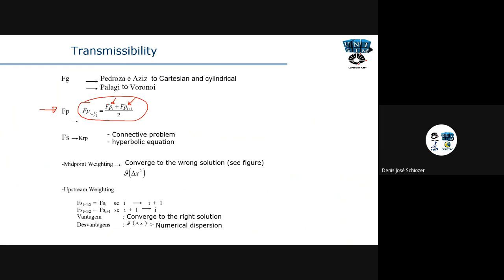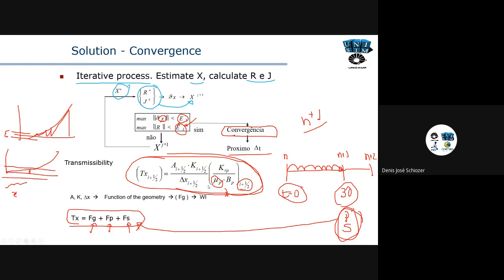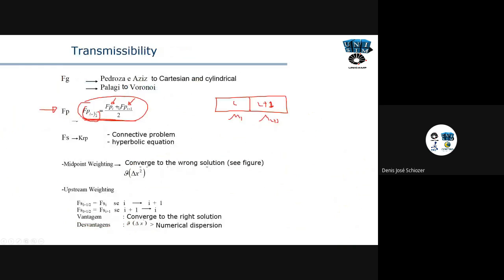So the viscosity between these two blocks can be calculated as an average viscosity between the two blocks, okay? Remember, if I have two blocks here, i and i plus 1, and I'm solving numerically, I have viscosity i and viscosity i plus 1, but I need the viscosity at i plus half, right? Because it's this term that I'm writing here. Oops, I'm sorry, I need the viscosity of the phase at i plus half. So I calculate it as an average of this function.